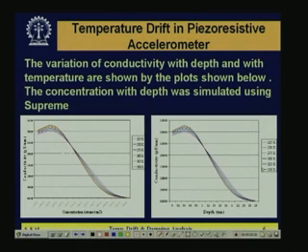Now, that means to reduce the temperature variation, one parameter is the proper selection of the doping concentration and junction depth, so far as the mobility variation is concerned, the change of resistance with mobility variation. We have to select the doping concentration and junction depth properly so that temperature variation of the conductivity or resistance should be as minimum as possible. So, now this is the TCR.